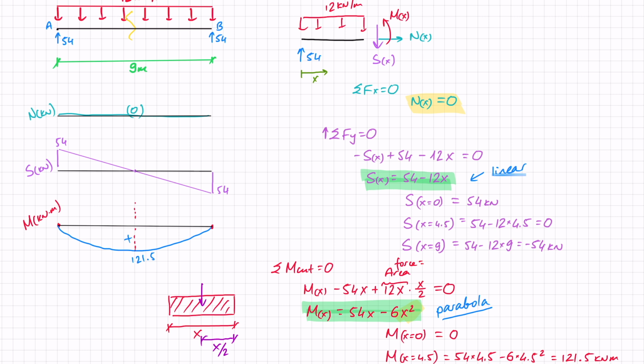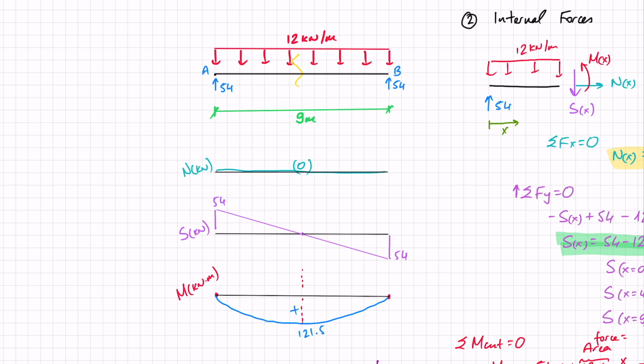The second thing we want to see is that when our shear passed through 0, so this point here, this was where our maximum moment is, here. And those things are very important, and they are apparent once we learn what the connection between shear and moment is. You might already be able to spot this. But those are a few important things to pay attention to. Let's just zoom in one last time to have a look at the results for a beam under a UDL.